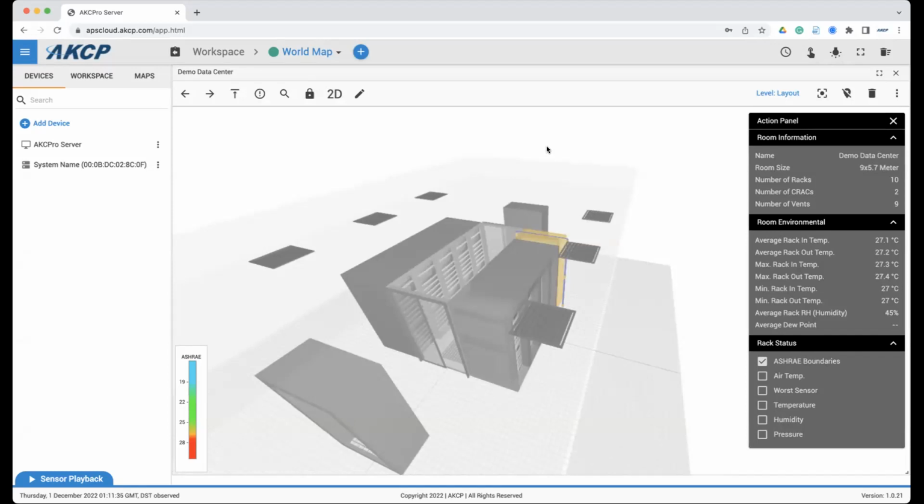In more traditional CFD, the CFD that we added there is a snapshot. We call that a steady state. So it takes one moment. Usually, when you want to model for changing your room and placing your rack, you do what's called transient.